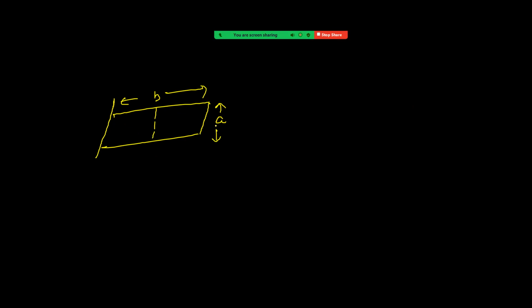Right. So here first of all, what I am doing is taking the torque equation about this axis. Because the plate is not rotating, plate is not rotating means we can take net torque must be 0. So I'm taking about this axis net torque equal to 0.